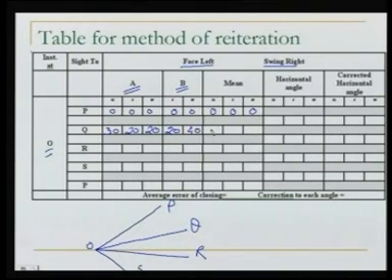Well, we will take the average of these two, so 30, 20 minutes and 30 seconds. Now what it gives you, we can similarly write the observations we are recording for R and for S also. And finally, when we close the horizon, as we go back to P, we will again record the reading here. Maybe this reading is 0, 0 and 20 seconds. Well, there is some error, 0 and 20 seconds.